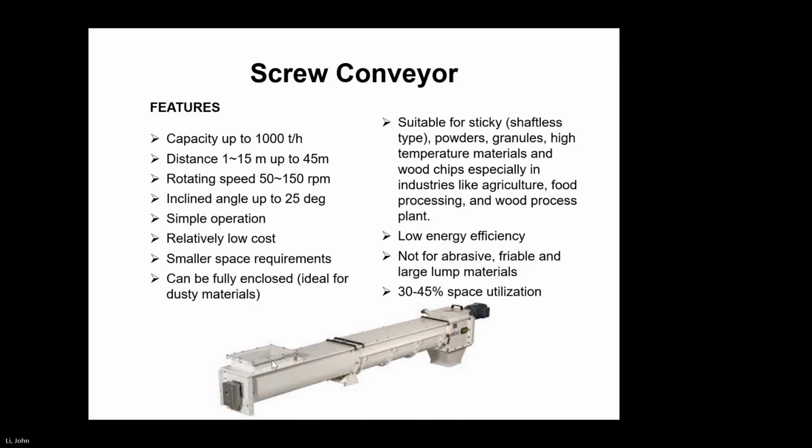Because of the nature of this arrangement, usually one shaft with middle support makes a screw conveyor. If it is longer, the shaft will have an issue with deflection. So it is mostly used for shorter distances.